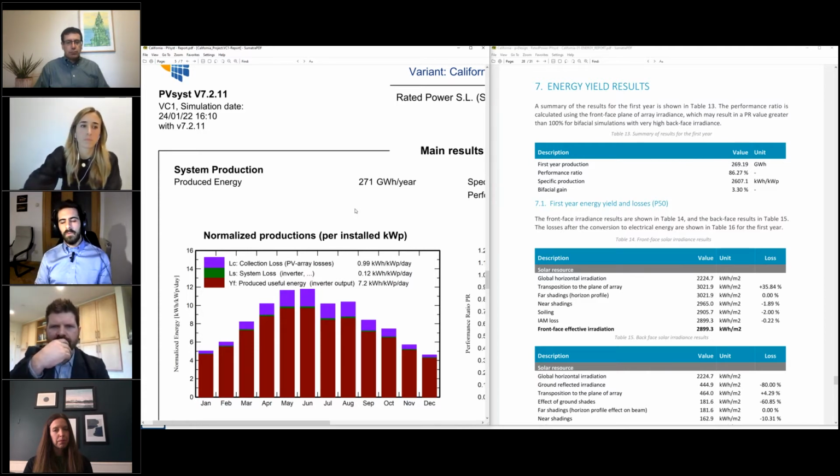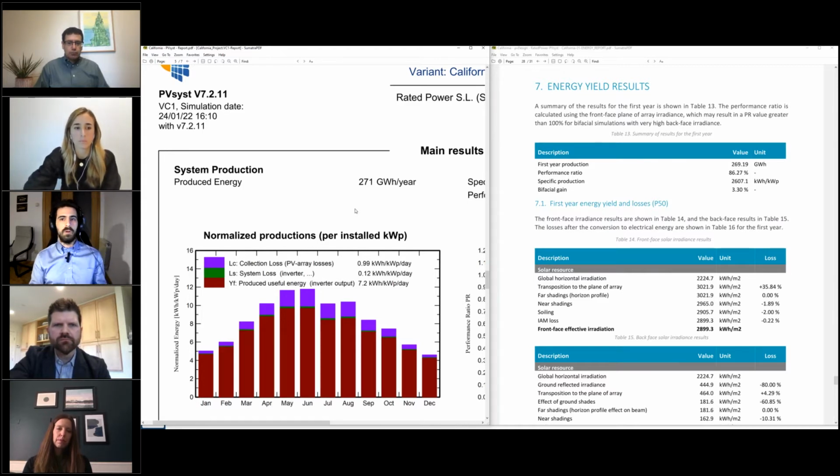But also, when you set up the configuration in PVsyst, it's really useful to understand what the equivalent configuration is between PVDesign and PVsyst, so that you can understand better how PVDesign works. So for example, you need to use a flat scene for the shading, and you need to use the "according to module strings" option in that dialog. And also, you need to set up backtracking when setting up the tracker. All of those little tweaks in the configuration are useful to understand how the two softwares compare, right?